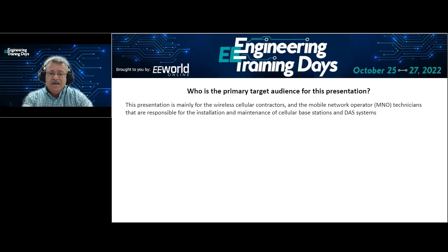As you go higher in frequency, let's say you're working in a lab with benchtop vector network analyzers and you're working at 40 gigahertz or 60 gigahertz or higher, these principles actually are more important at the higher frequencies. But you'll see how it impacts even at cellular frequencies. There's quite an impact when you have a poor quality adapter.